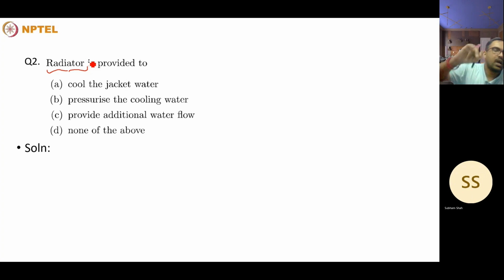after exchanging heat with the incoming air. So this is the process which was used in most of the engine vehicles in the previous era, where the heat taken out by the water jacket will be released in the radiator to get a cooler water to complete the circulation around the cylinder. So the answer is the radiator is provided to cool the water from the water jacket.